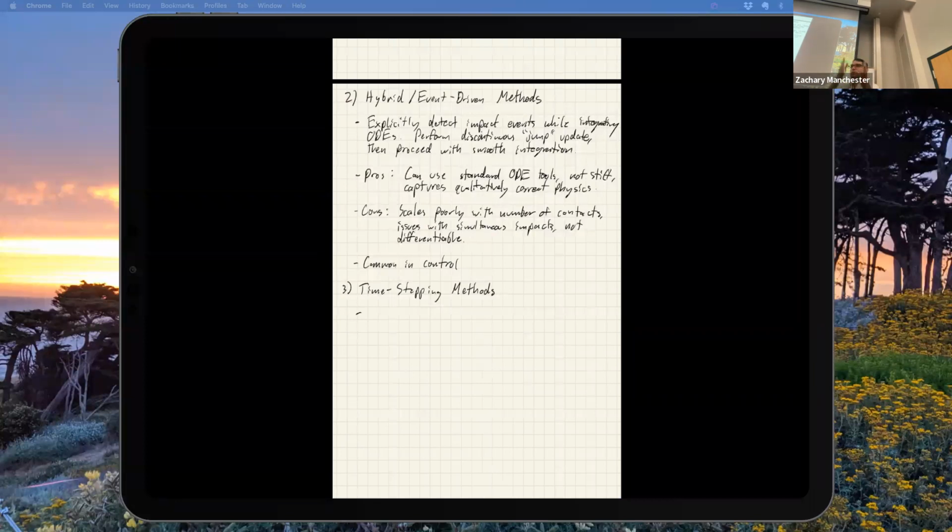If I have a fixed step size, H, I have a contact constraint that says the foot's not allowed to go through the floor. I explicitly check the constraint at each knot point, each t_k. At each step, I'm at t_k now, solving for x_{k+1}, and I check the contact constraint at x_{k+1}. The constraint says phi of x_{k+1} has to be greater than or equal to 0, like the foot can't go through the floor, an inequality constraint.